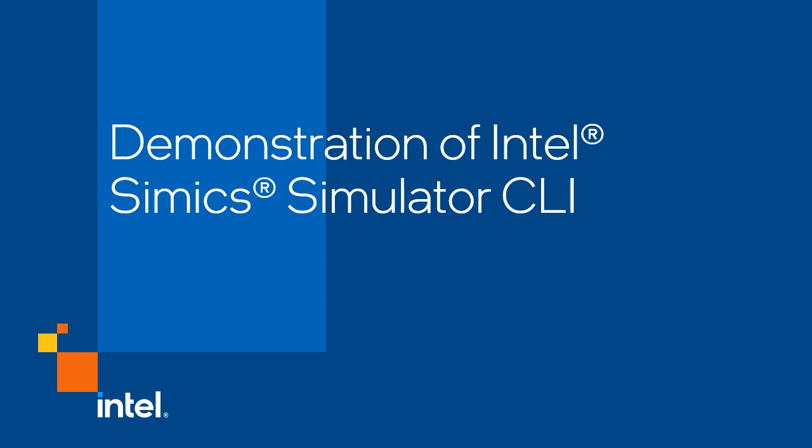A file can be created to go back and take a look at the results of a debugging session or just the history of the Intel Simics CLI. Let's take a look at a couple of examples of use of the CLI. Run or stop can help you run the simulation from the CLI, using the commands run or stop directly in the simulator.